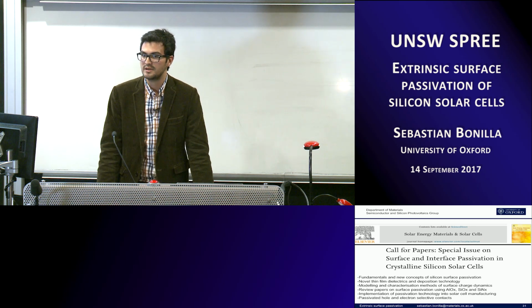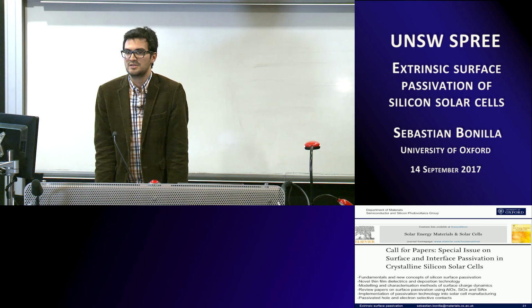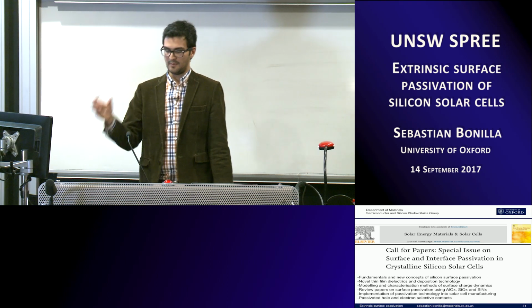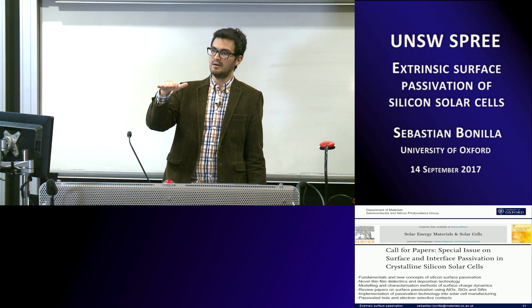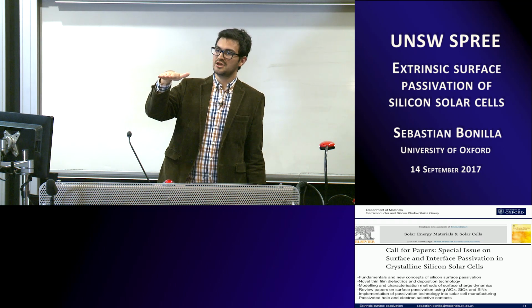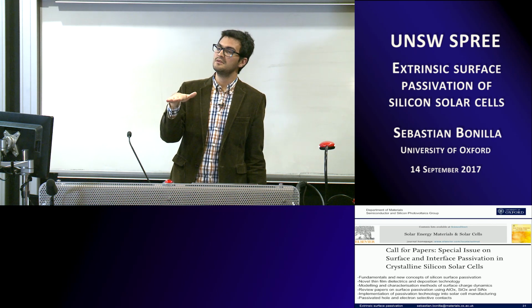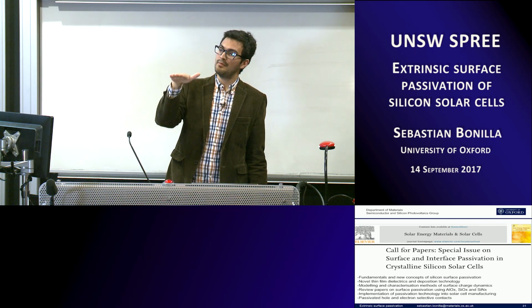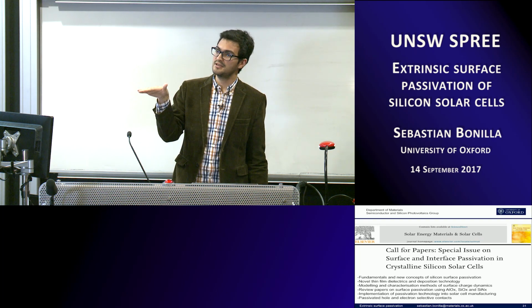We didn't quite measure it directly, but there is a fairly easy measurement that we do: we deposit the charge, and then we measure the Kelvin probe surface potential. What we see is that the value of surface potential starts going down quite quickly, but it doesn't go down to 0. It goes down by a bit, but then stays at a certain level.